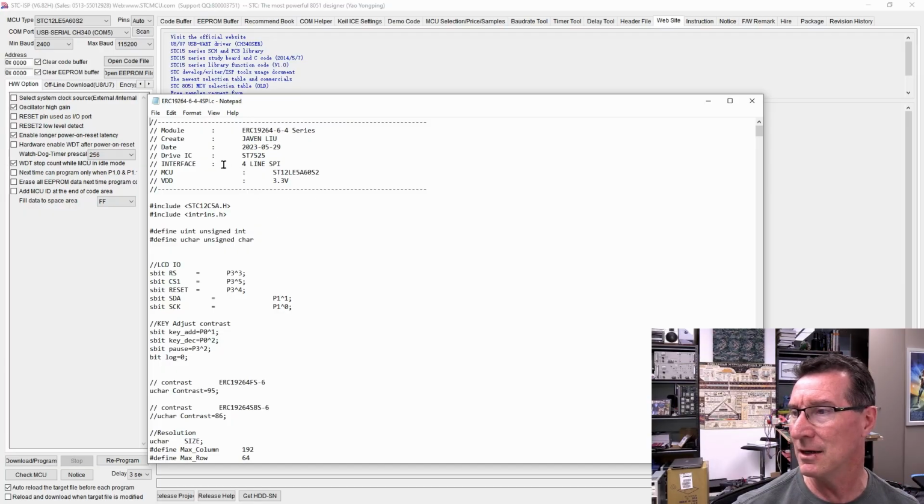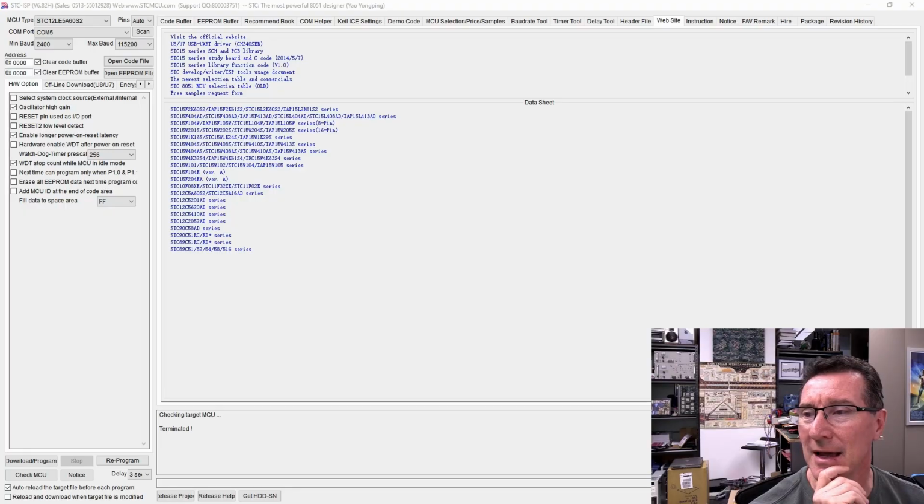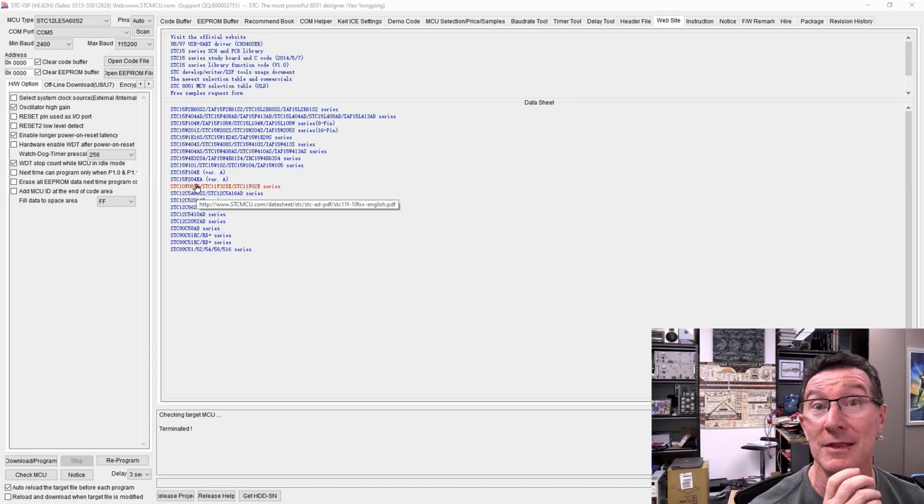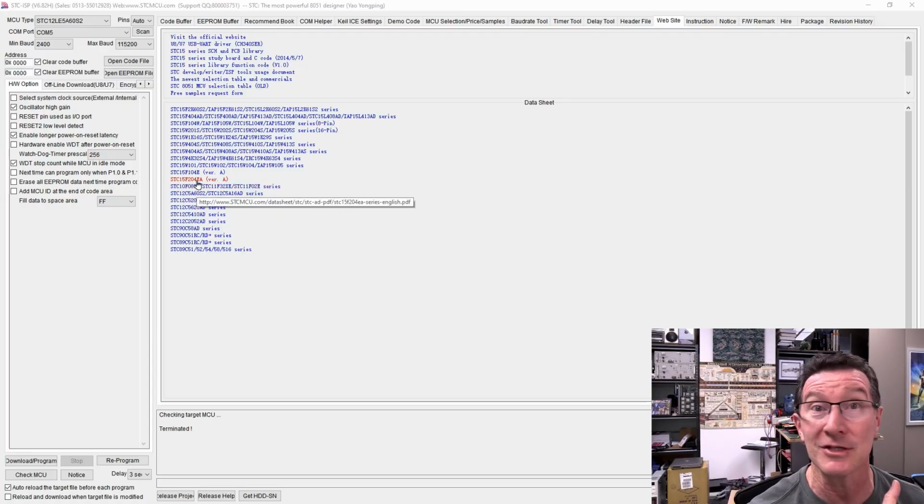But I need to generate, like, do I have to go find myself an 8051 compiler that supports this? Doesn't make sense. This is just the programmer software, but I can't find the hex file. So without that, I'm up the creek without a paddle. At this stage, I have no real desire to go and try and find an 8051 compiler that supports this chip, and then, sure, you can compile it, but have you got the right fuses and everything else, whatever that micro needs? It would have been great if they just supplied the hex file, and I could just burn it in, but it doesn't seem to be on their website, so I'm going to have to contact them.